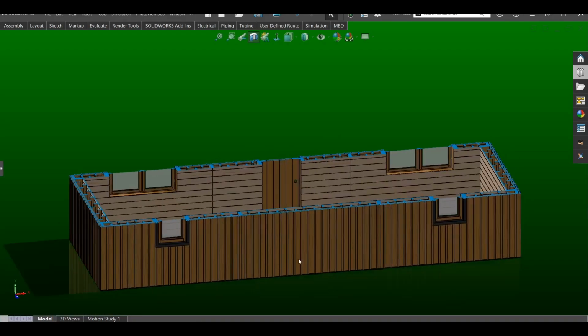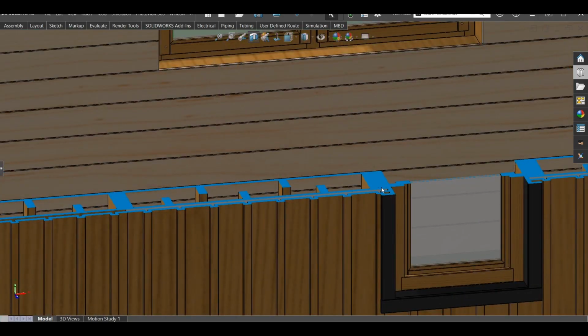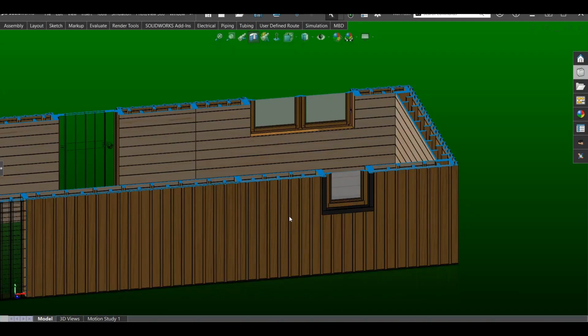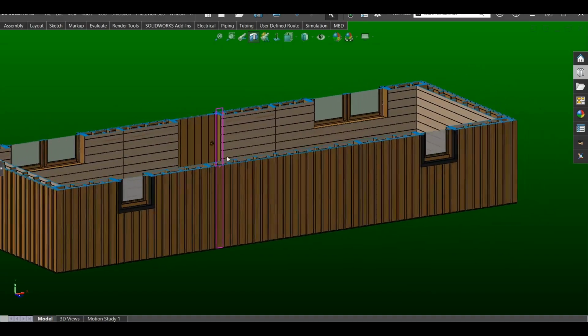And so as I showed you with the foundation, you get that pocket layer of 2x8, 3/4 inch, and then a 2x8 sandwich in between. So you get that 7-inch, and you get the same thing here on the wall. So you got your 7-inch on the floor, plus you're elevated from the ground. So that's less thermal bridging.